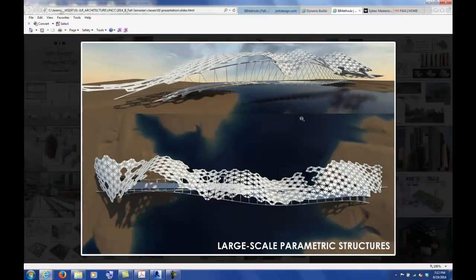And then same thing with the canopy structure that was also parametric. What's nice about that is there's actually 3 or 4 components here. There's the bridge component, the pathway, then there's the tensile structure, there's the main structure, and then there's that particular panel that actually makes up that canopy structure, to give it that tectonic look. Those 4 components were only modeled in Revit and then applied to this complex surface, and then you could sit there and explore and move these things back and forth over different lengths and so on, and you get different variations without having to remodel it every time.